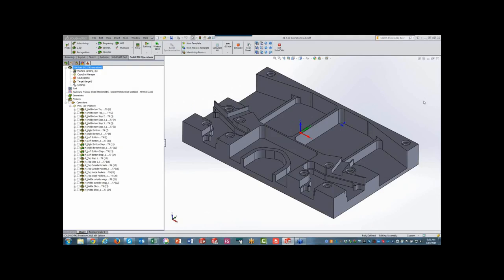I'll give you a simple example. If we take a look, for example, at this area alone, this is a very simple area just between here and here. But if the person wants to machine it, he has to study it and say, you know what, I have a step over here. Well, I first have to machine it down. I have to create a geometry just for this area, just going down to this step. He has to think about all these things. And then he has to think, okay, then I still have to complete this area, and then I have to complete the third area over there. These are different technological issues that the person has to study in order to machine the part properly.